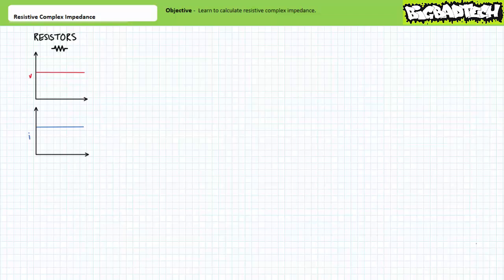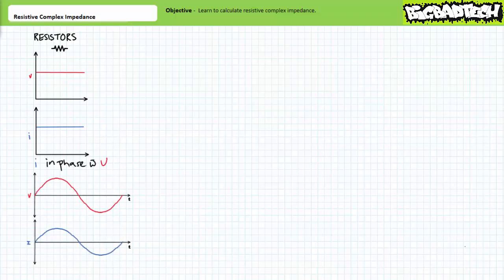In summary, resistors follow Ohm's law, a phenomenon that relates voltage, current, and resistance. Resistors dissipate all power supplied to them in the form of heat and are not energy storage devices. Even our initial discussions of resistors and sinusoidal AC sources demonstrated that resistors consistently follow Ohm's law and voltage and current are in phase with one another. Capacitors and inductors, in contrast, are reactive elements and can momentarily store and return energy. As such, the reactive nature of these energy storage devices needs to be accounted for.